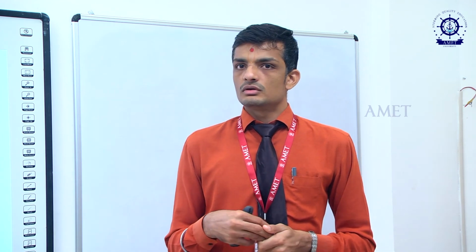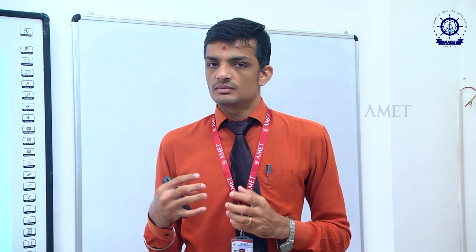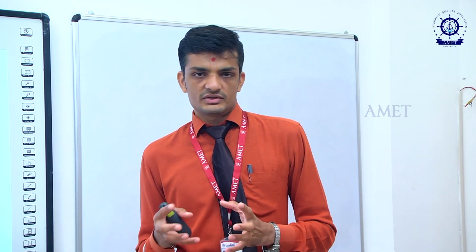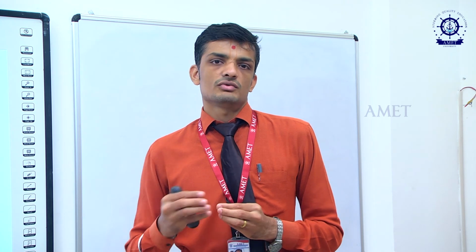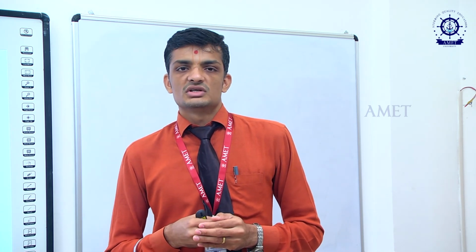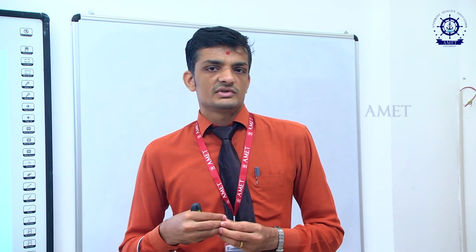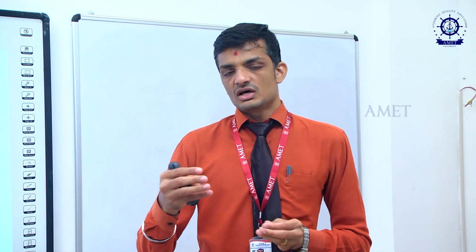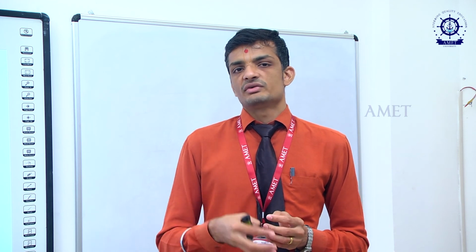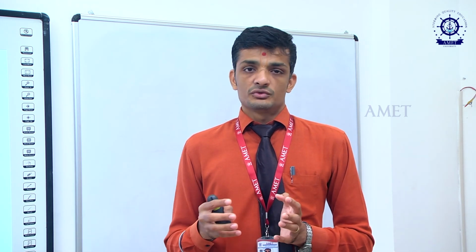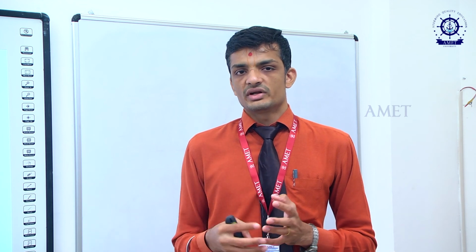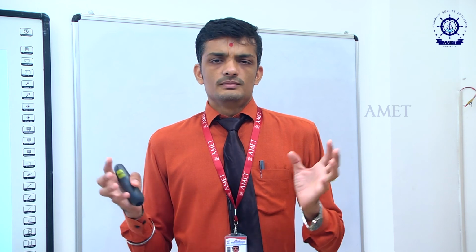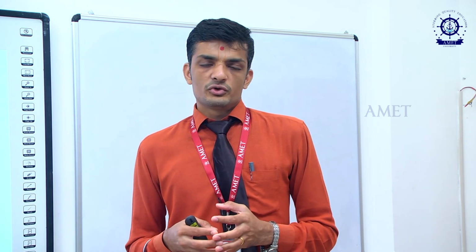Then load. So this was about the problem specific part. You form your element matrix, you form your stiffness matrix, a global stiffness matrix. Now what kind of load are you going to apply upon that? Is it going to be a point load, surface load, or volume load? That vector you have got to form. So each element will have a load coming on it, so for each element, one load vector will come. Similarly, how you merge stiffness for elements to make a global stiffness matrix, the same approach is to be done for merging all the loads and making a load vector.